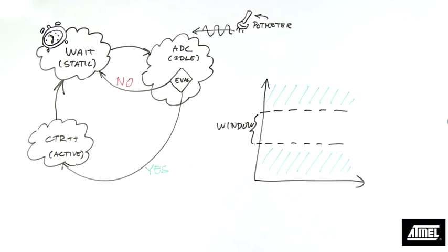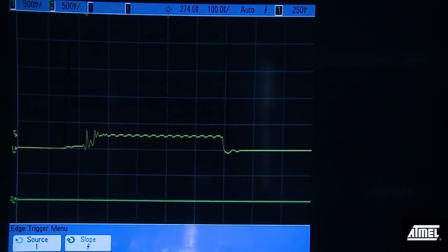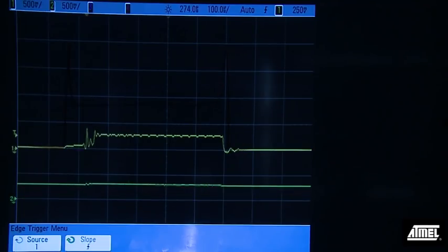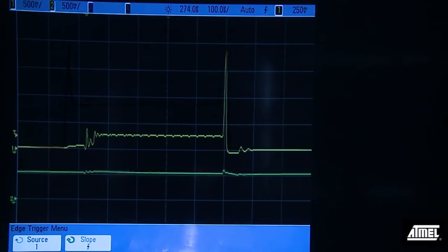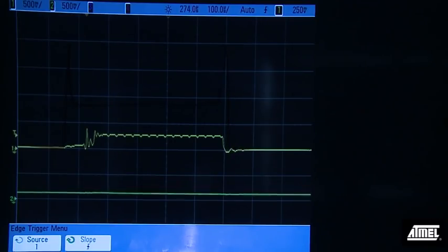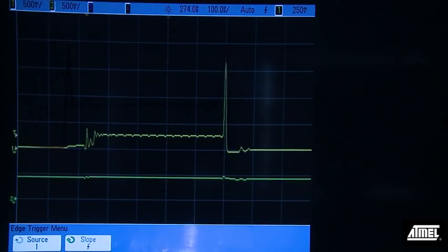Now let's take out the oscilloscope once again. This time it's different. Watch when you go above the threshold. Near the end of the pulse, the CPU is activated for the processing, and this peak is the same height as for the classic mode. Of course, our processing in this case is just incrementing a counter, but the point is proved.